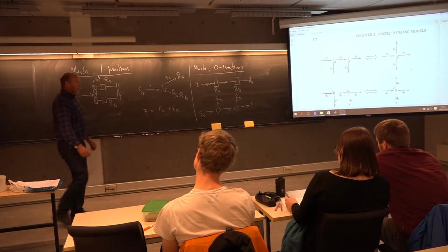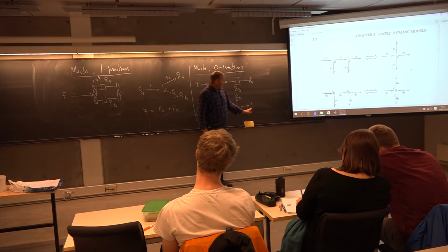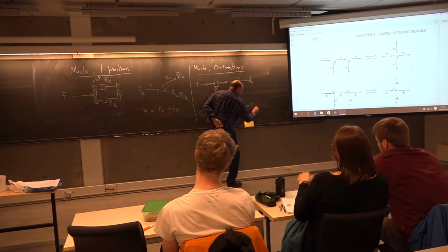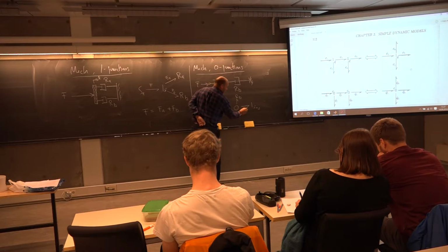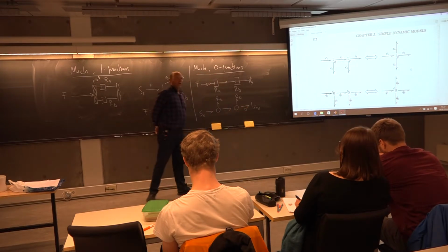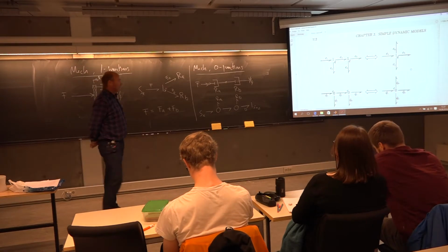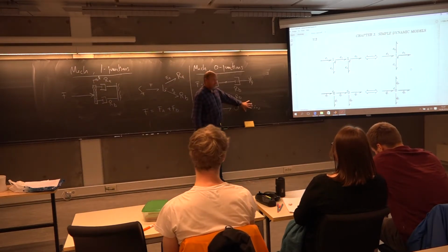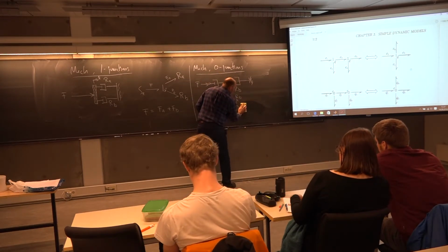But here you can now start to simplify, because a solid wall doesn't move, hopefully. So the x dot, the velocity here, is 0, meaning the flow here is going to be 0. That means you have no power entering the wall. So this bond hitting the one junction can be removed. So you can forget about the wall.